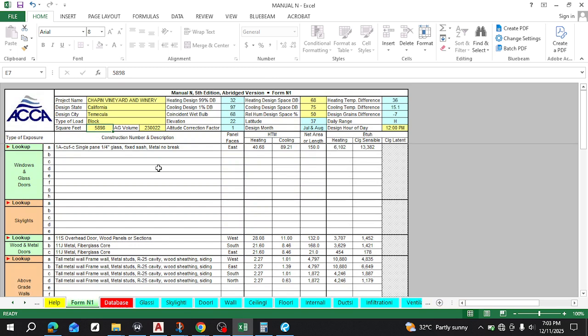This is where everything meets, everything comes together. This is your final document, what it should look like, right? If you also notice, this is the design month, this is the design day. Basically it's trying to estimate the amount of heating or cooling that building will need. And this design month is the peak period in the year where it's expected that the equipment you're selecting is supposed to perform at its maximum, right? So it designs with that in mind so that when the other less demanding times come, the equipment can still function, right?